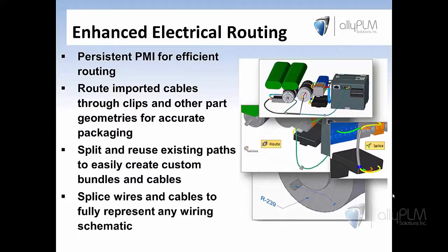We just took a look at ST8's enhanced electrical routing functionality. This includes persistent PMI, routing imported cables through clips and other part geometries for accurate packaging, splitting and reusing existing paths to easily create custom bundles and cables, and finally the ability to splice wires and cables to fully represent any wiring schematic.